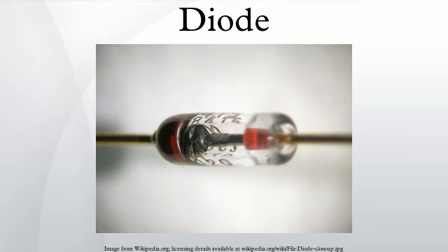Reverse recovery effect. Following the end of forward conduction in a p-n diode, a reverse current can flow for a short time. The device does not attain its blocking capability until the mobile charge in the junction is depleted. The effect can be significant when switching large currents very quickly. A certain amount of reverse recovery time Tr may be required to remove the reverse recovery charge Qr from the diode. During this recovery time, the diode can actually conduct in the reverse direction.